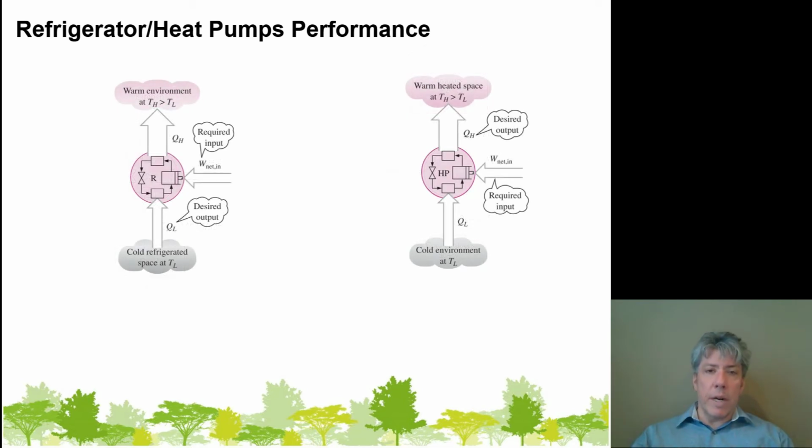So we can make these a little more abstract and just consider them as devices that are pumping thermal energy from a low temperature source to a high temperature sink. And of course the goal of the refrigerator is pumping from the low temperature source. The goal of the heat pump is pumping to the high temperature sink.